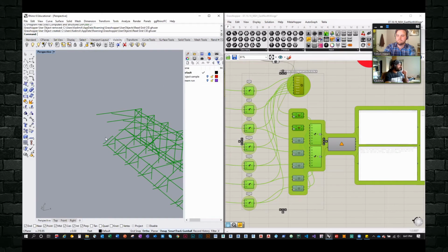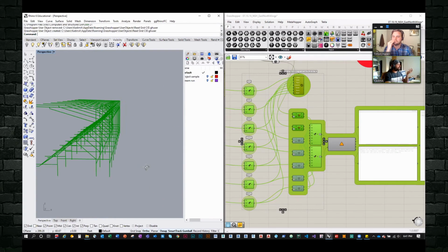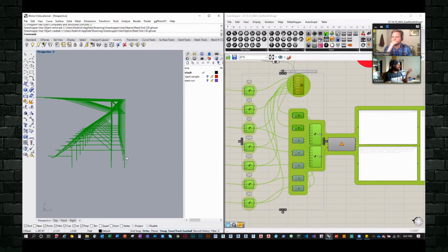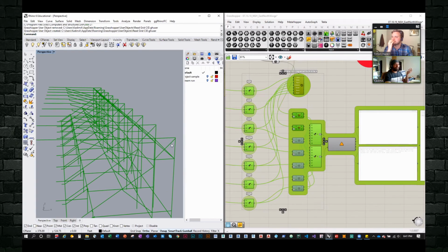So if design changes happen, which happened on this project, at some point this whole back grid shrunk by, I think, 2 feet or so. And in Revit, controlling all these points is not impossible, it's just really painful and tedious. Here, all I had to do is update the grids file, because that grid shifted back by 2 feet, and the entire structure updated. Then all we had to do is regenerate the Excel spreadsheet and send it back to Revit, and because the indexes were matched, it was just a mere update instead of a rebuild. I have done rebuilds as well.